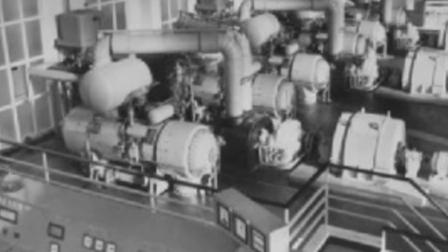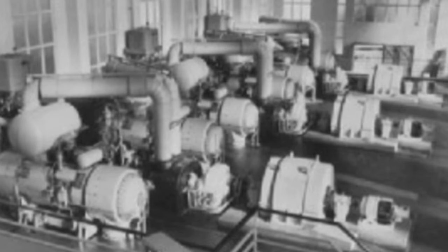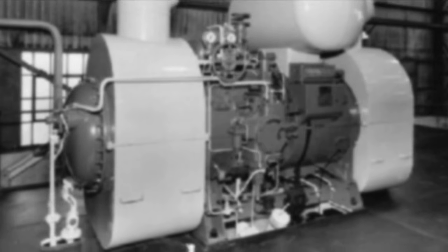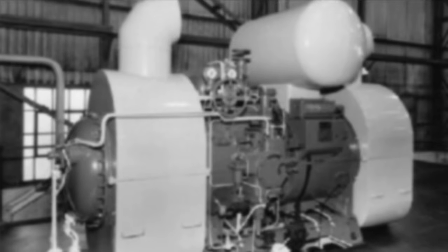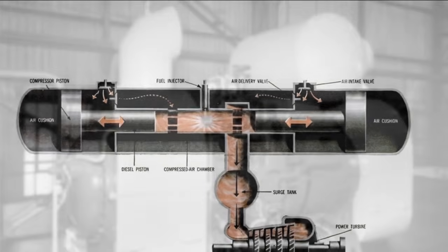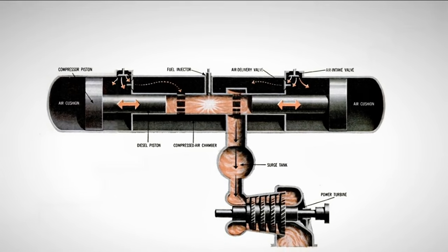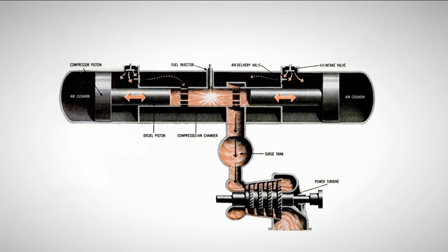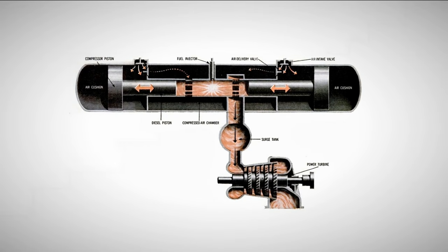Free-piston engines were completely balanced machines, virtually free of vibration, allowing them to be installed without the need for massive foundations. A common trick used during demonstrations was to place a pencil or coin vertically on the horizontal surface of a running engine, and they wouldn't fall. The simplicity of the design and the relative lightness of the components significantly simplified the manufacture, maintenance, and repair of these machines. Their cost was almost half that of diesel engines of the same power.